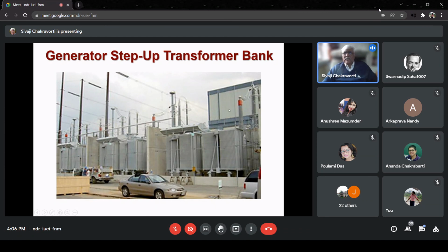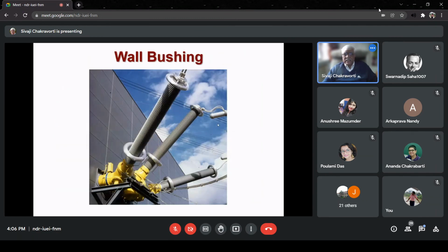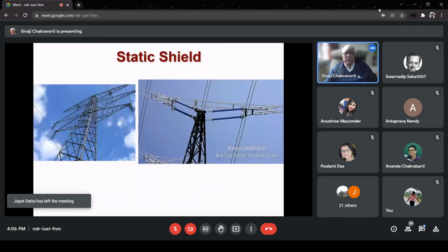But here you see there is only 1 bushing, this red color. So that means it's a single-phase transformer. So that is another way of looking at it and taking immediately an engineering decision. See, this is a 3-phase equipment, or I can show you an actual transformer.